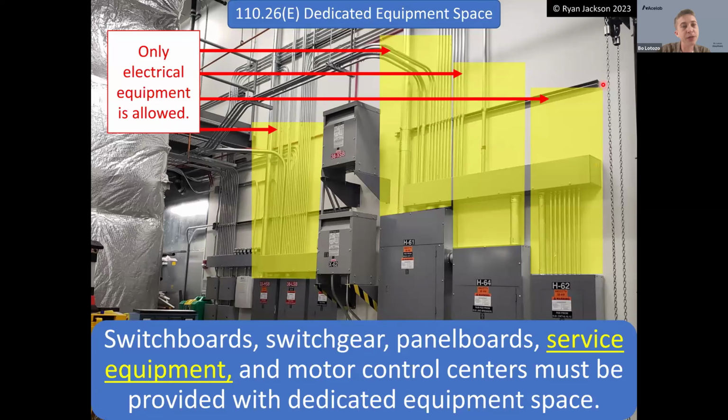All right. What is the difference between an electrical room that requires 1 hour versus 2 hour construction? UPS battery rooms typically require the 1 hour. Are there any 2 hour requirements for electrical rooms? The only time that I can think of is when you have a medium voltage transformer vault. And a transformer vault is supposed to actually be 3 hours, not just 2. So if you look in the NEC at 450.42, there's some criteria there that requires it. But transformer vaults really aren't that common either.